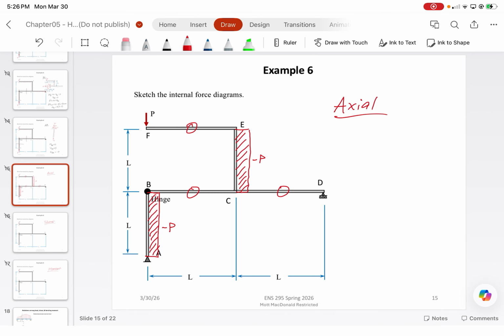That's why I always work with colors and make sure that the sign conventions are clearly indicated, just to avoid any type of confusion. Okay, so you just denote if it's above or below the reference fiber, whether it's positive or negative, and you just follow that convention, correct? Yes. Once we start getting into deflections and deformations, you'll notice that the bending moment diagram and shear force diagrams will help you with figuring out how the structure actually deforms. So I will usually draw a deformed shape just to show how the structure is supposed to deform. Okay. All right.